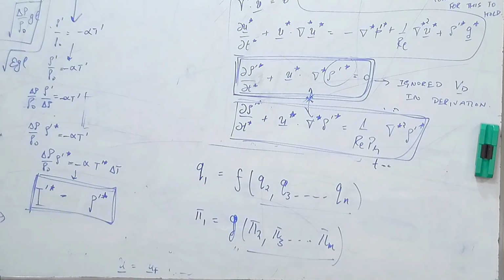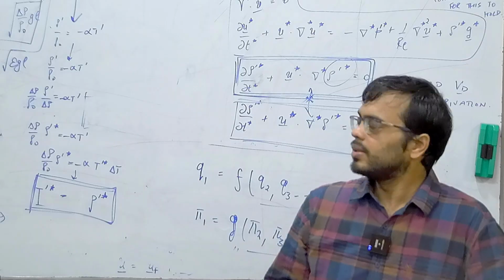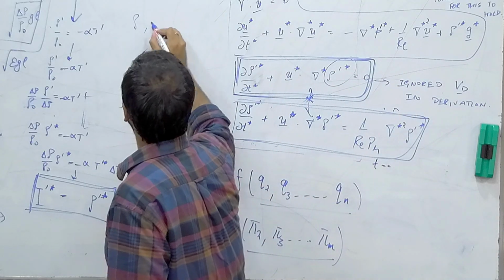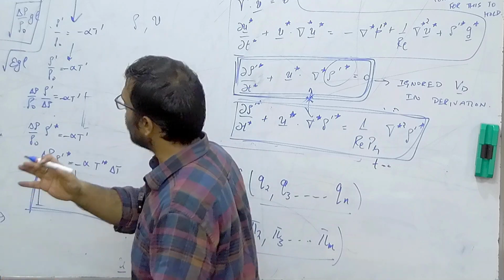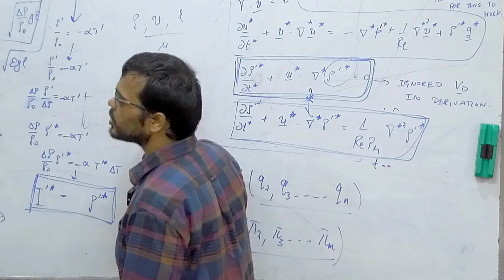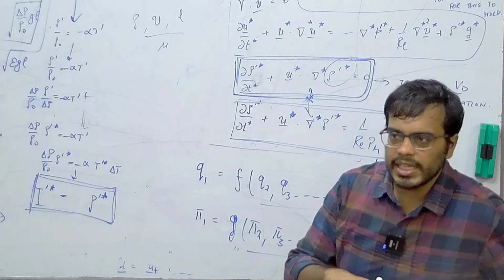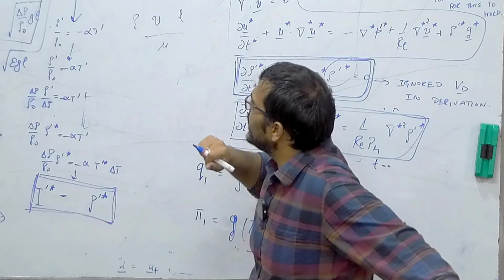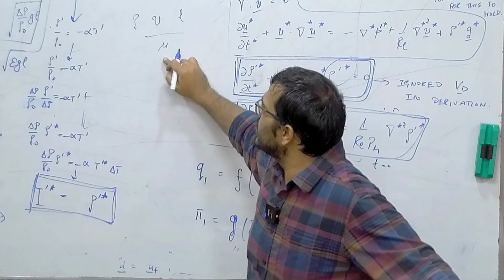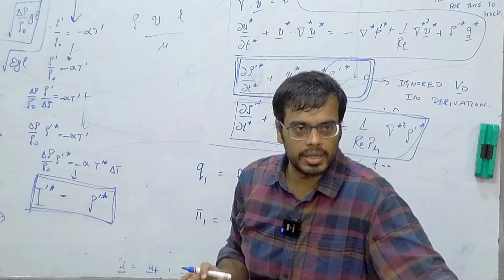The idea is you do not need to, for example, let us say I give you a flow which has some density, the flow velocity is known at some point, the length scale of the flow is known, and the viscosity of the fluid is known. Now I change these quantities such that, let us say the flow was in water, I change it to flow in honey, so that I change my velocity and length scale accordingly, so that this ratio remains constant.